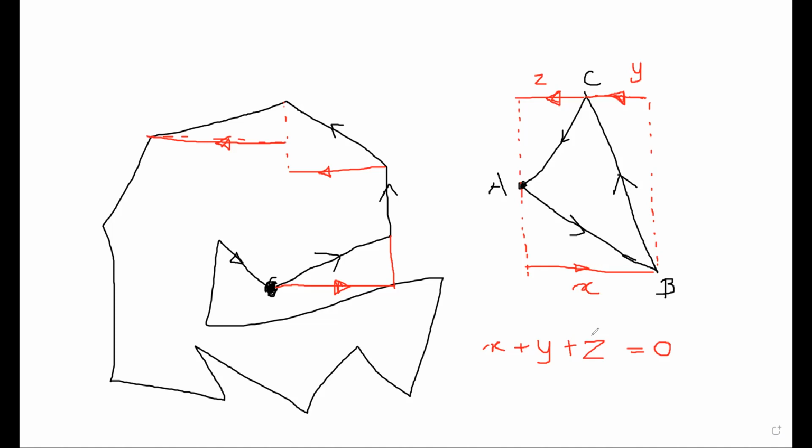We know we have moved along a closed polygon, and we know if you sum up, it should be 0. But when you add, it won't be 0. So 0 is the expected value, or we call the actual value. If you have a perfect set of measurements, then we know it should be 0.